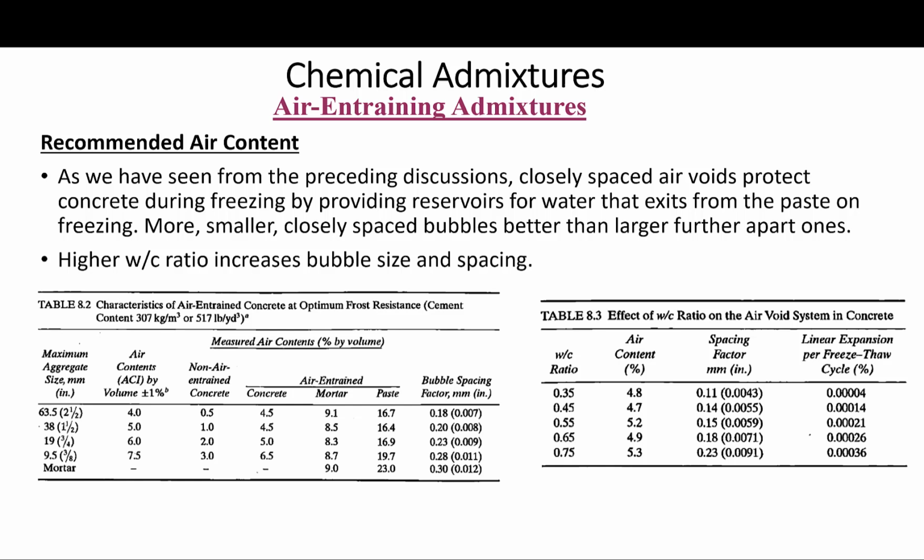Remember, we said the spacing factor is a certain number such that for any point of the paste, there should be an air bubble within that distance. But you have to remember, in practice, we have to rely on total air contents, because the bubble spacing is not an easy quantity that you can really quantify when you recommend a certain dosage. So in practice, we have to rely on total air contents.